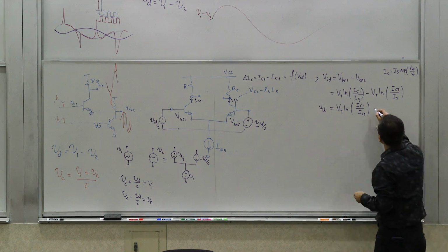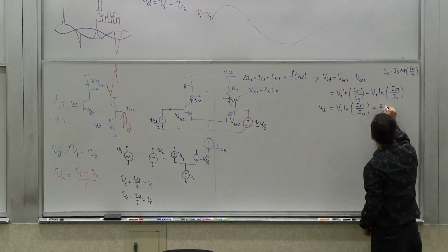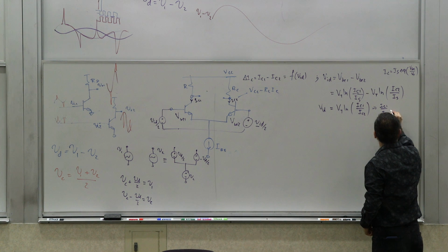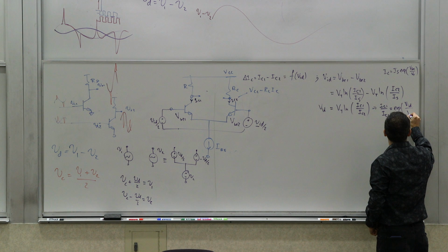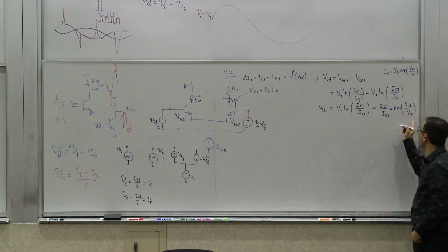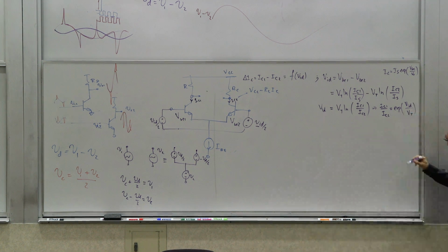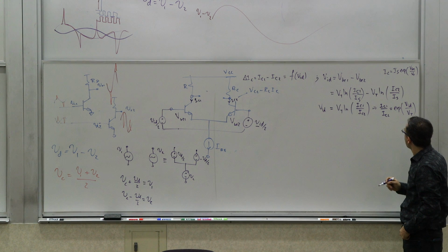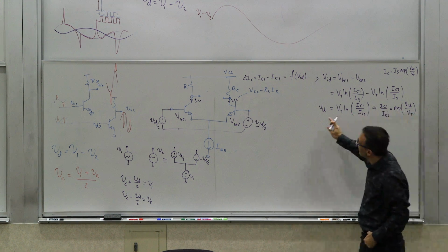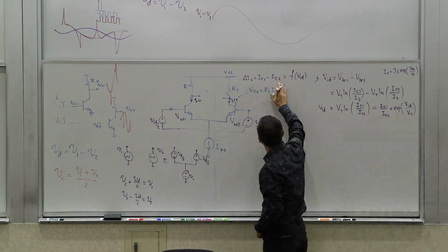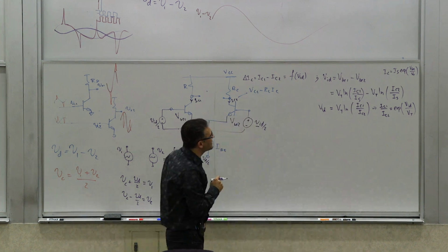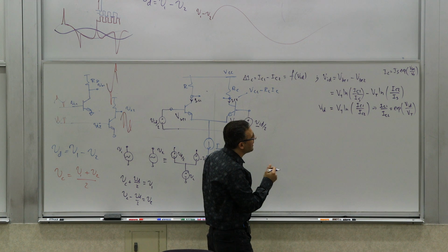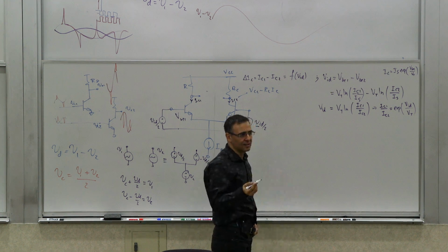So, of course, you can take this and you can invert it. So you can write it as IC1 over IC2 equals e to the VID over VT. This is the thermal voltage. OK? So that is OK, but I still haven't gotten to this. I'm trying to find what's the relationship between the difference of these guys. Is this the only thing I know? IC1 over IC2 is exponential. So I know that the ratio of IC1 to IC2 is an exponential.